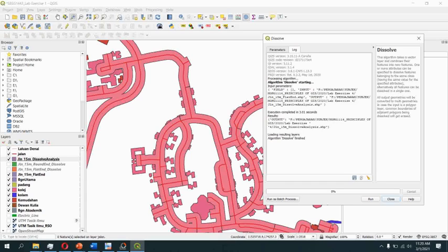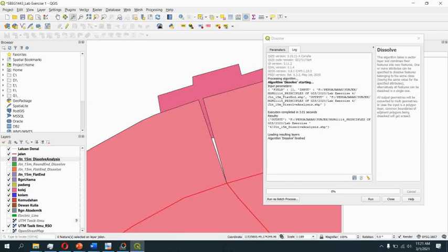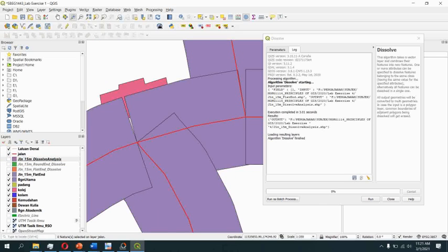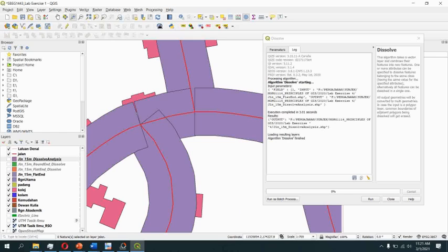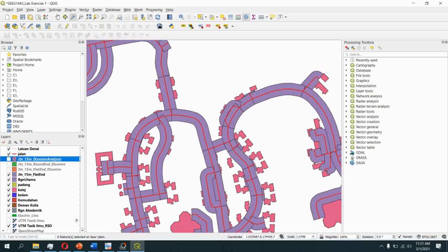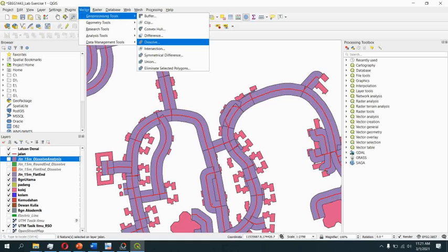Alright, so what will happen is it will give you all the dissolved, connected data. From this data, it will dissolve all the segmentation, all the boundaries between polygon and polygon. Okay, that's a simple one. So we already discussed a little bit on dissolve. You can try with another data if you have it. The next one will show you how to do clip.